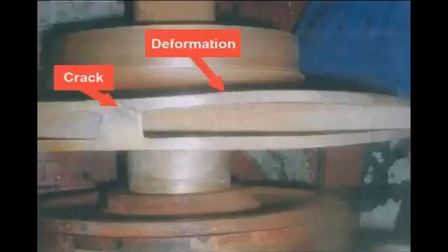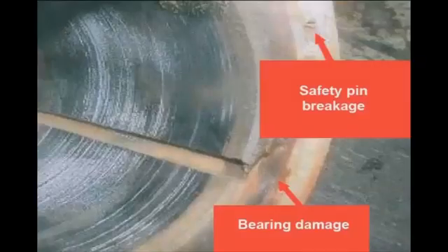Here's an example of cavitation. It occurs in the periphery of the bell mouth during discharge from the ballast tank. In the event the suction speed increases as the water level drops, cavitation is prone to occur in the periphery of the bell mouth. When it comes to pumps, cavitation is liable to occur in areas around the impeller. Bubbles generated can cause abrasion, and vibration can damage the impeller.